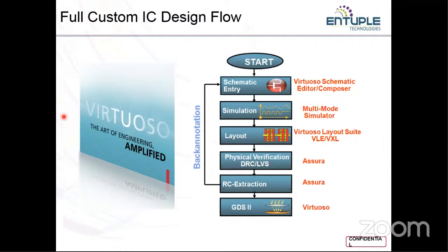So you have different layers: polysilicon, metal, silicon dioxide, N well, P well, N implant, P implant, and different types of metal layers. Each layer will have its own set of rules, like minimum size and minimum spacing.